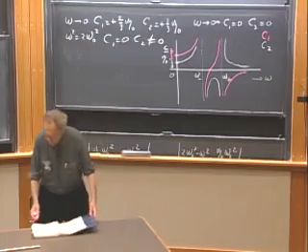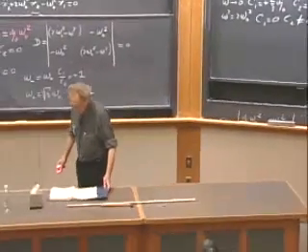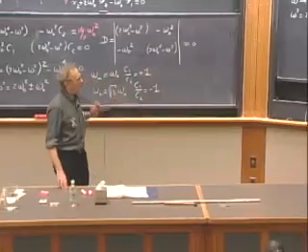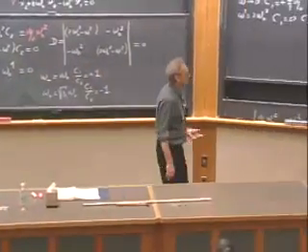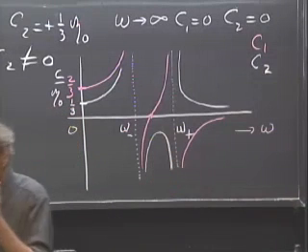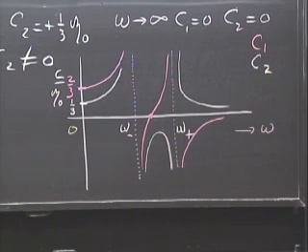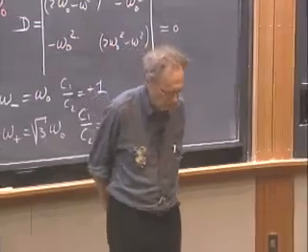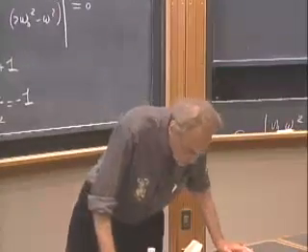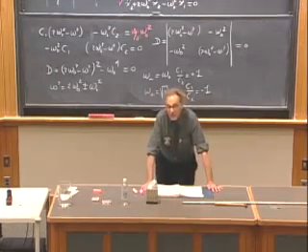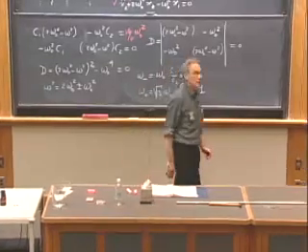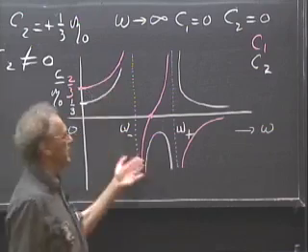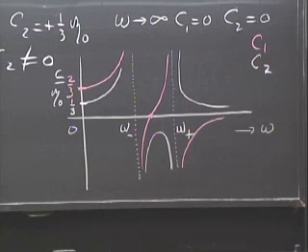Now we ignore damping, and because we ignore damping, we get these unphysical infinities when you hit the frequencies omega minus and omega plus, these resonance frequencies. Now if you include damping, then the solutions become extremely complicated, but of course you avoid the infinite values, but the resonance amplitude can still be very high. And so these plots are still very useful, provided that you don't interpret the infinities as being real, but something that is very large. If Q is high, then of course the amplitudes are enormously high. And this can lead to destruction.